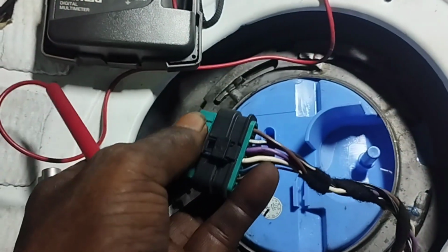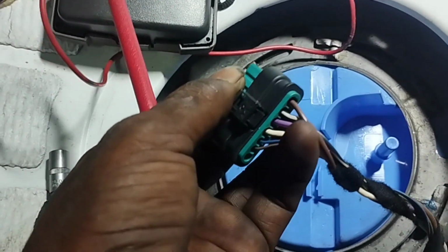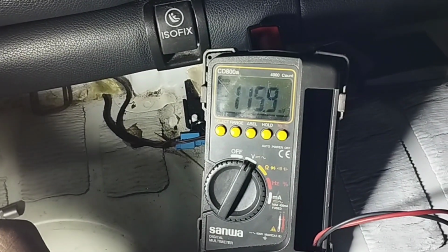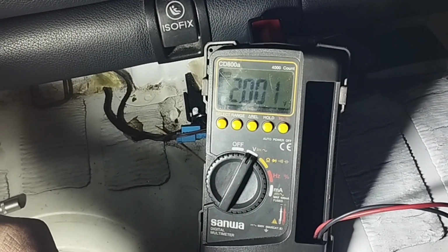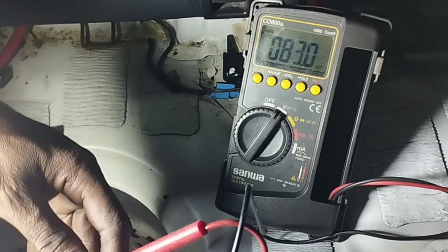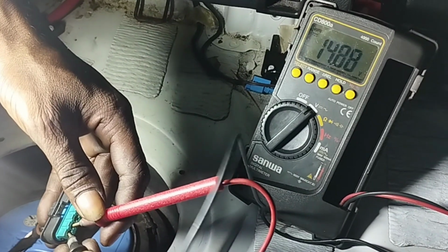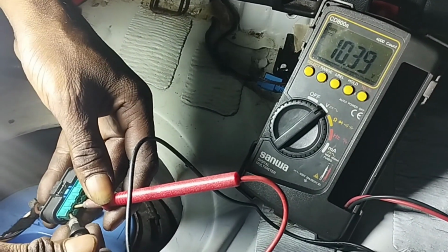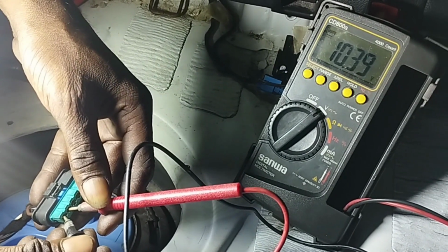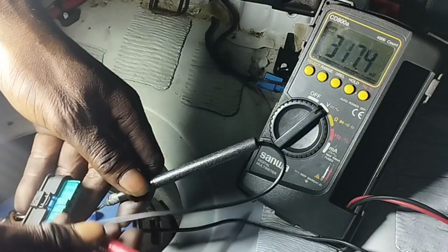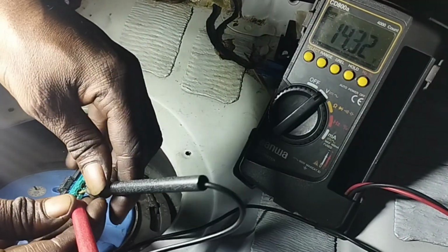The number 2 wire in the fuel pump socket is the positive supply voltage and all other wires are the ground body earth signal. Now I will test the ground body earth signal of the socket. Connect the red cable of the multimeter to the second wire of the socket, and connect the black cable of the multimeter to the number 1 wire of the socket. Check that the ground signal line of socket number 1 wire is OK.